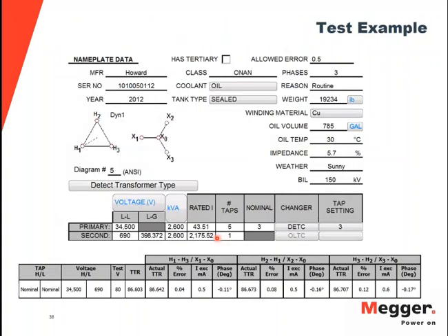Yes, thank you, Dinesh. And I'll add one more point on that too, is that when you're getting to that lower resistance, your connections make a big difference as well. If you're using those grounding studs or the little plug-in connections, and you're hooking to one spot of it, or if you're up even an inch or two higher on a different side, that could influence the resistance as well, because the resistance of that connection will add to it. But yeah, that was a good point. Thank you. Robert, your point was very valid. You are correct that even changing the connection a little bit can affect your reading. So that's a very good, valid point.